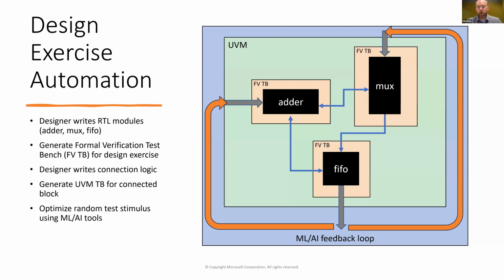And of course, when we're generating our stimulus and analyzing our coverage, we can collect all of this data, and this should be a kind of closed loop, right? I don't see why people need to be tuning random tests. The machines can do it with much greater fidelity and much greater accuracy, based on the nuances in the coverage data and the relationship to the input stimulus. So this is kind of the holy grail for verification.